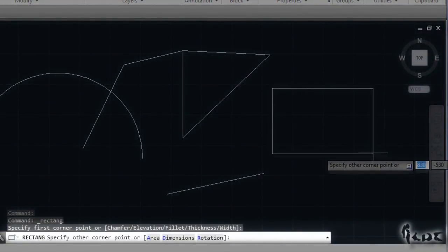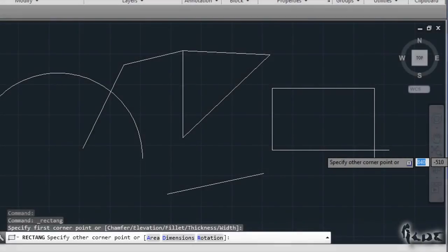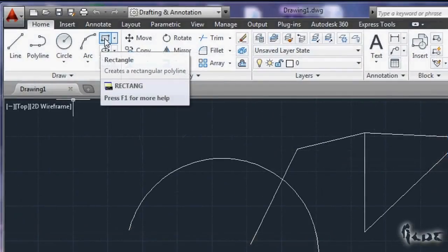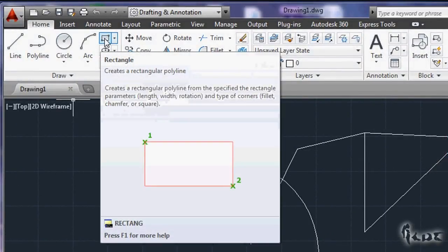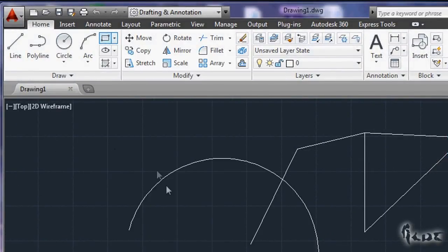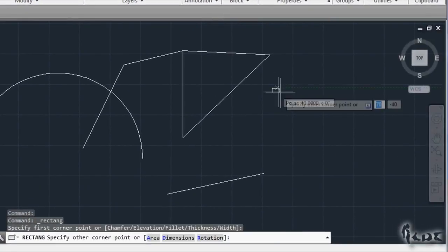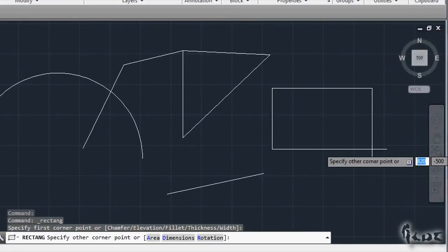Each time you draw or do anything, the command line will tell you what to do or any choices, which are indicated through brackets. Choose Rectangle. After you set the first point, you can put a precise area or rotation. If you want to rotate your shape, just type R in the white slot next to your pointer. This is used to type a command.